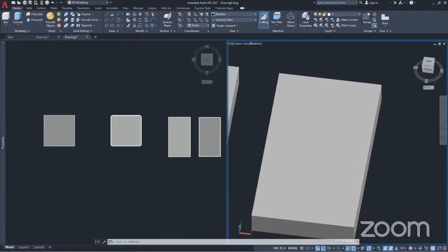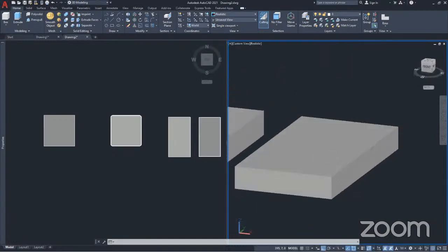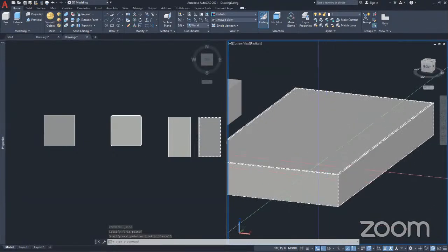Okay, yeah, I have it. Now the next thing to do is to actually press pull this object downwards. Yes, you press pull it downwards. Now who remembers the thickness? The thickness was 0.5 and the height of this box was how many? Let me see, I'll use a line to check that. I'll snap to this point and then drag upwards to this point. We have about, okay, yes, we have about 11.5. So if I take it down by 11, I think it would be nice.